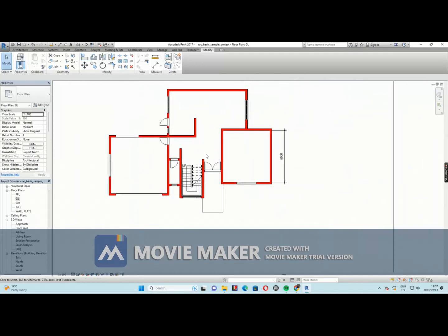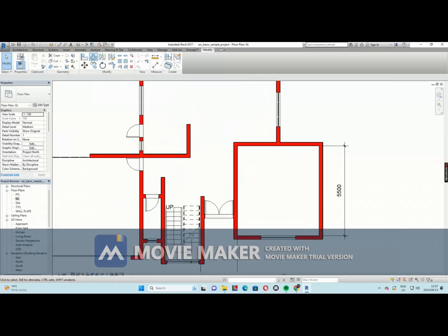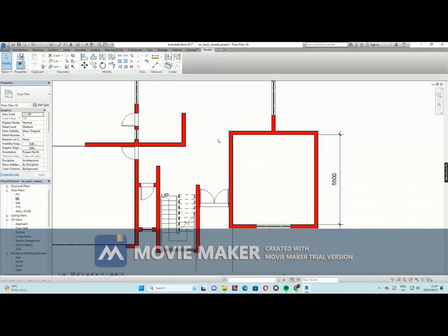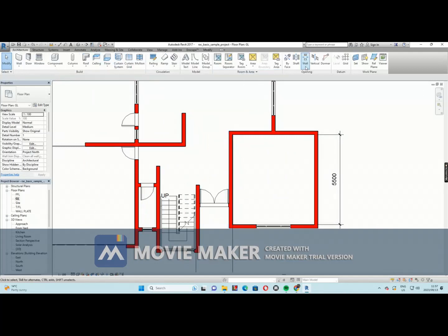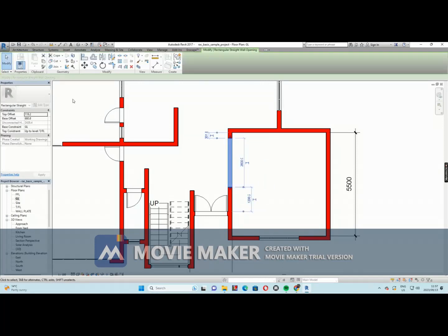Okay? If you want to cut an opening here, you come to architecture, wall. Then you click this wall. You cut from where? From here, maybe, to there. Depending. If you want to edit your cutting, let's say you want 2.6. A cutting of 2.6 is fine, then that does it. But this cutting, you must check it now. You must edit it. Top 0, from where?